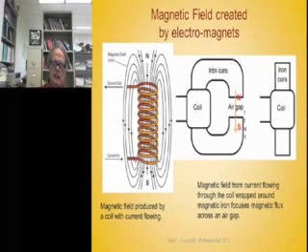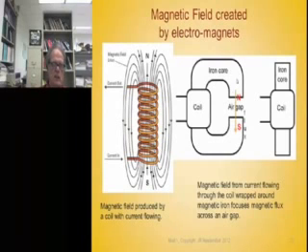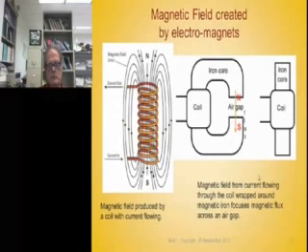And it doesn't take much ampere turns, or turns times the current flowing, to magnetize this iron, but it takes a lot more to magnetize this air gap, to get the lines of flux that are flowing from the coil in the core to jump across the air gap and go to the other side. But this is where this air gap is in the motor between the rotor and the stator, isn't it?